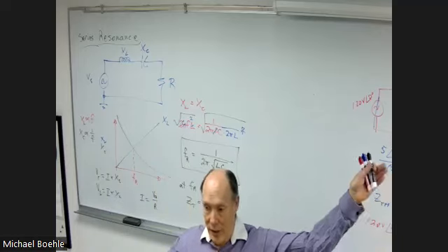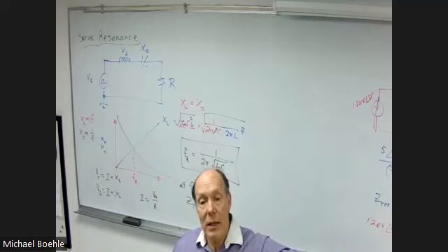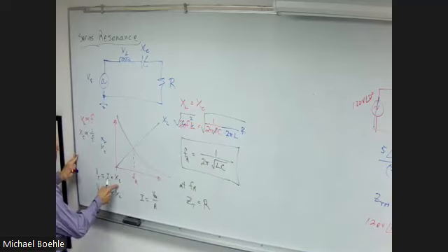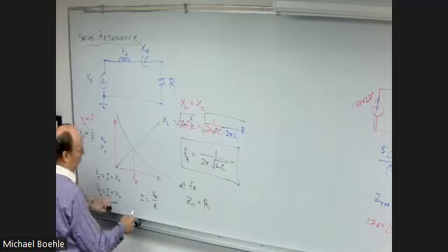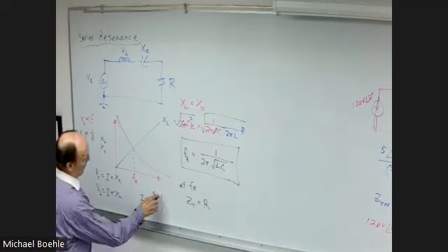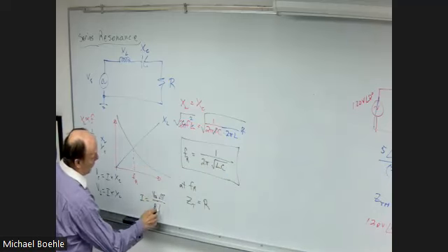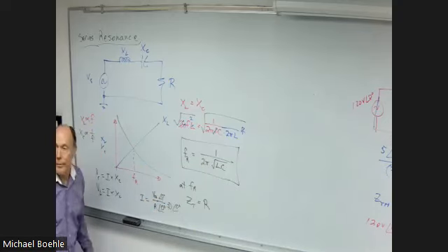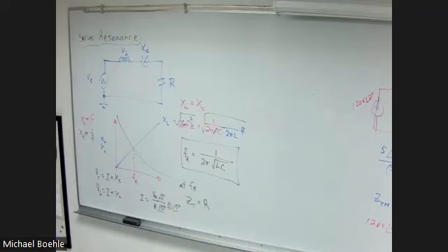Those two voltages will be what? 90 degrees one way for the capacitor, right? So my voltage across my capacitor goes to capacitive reactance. So what is the phase of the current? Let me back up real quick. What will be the phase of this current? Well, my source is at 0, resistance is at 0. The current will be at 0 degrees. You'll have no phase shift between the voltage and the current in the circuit.